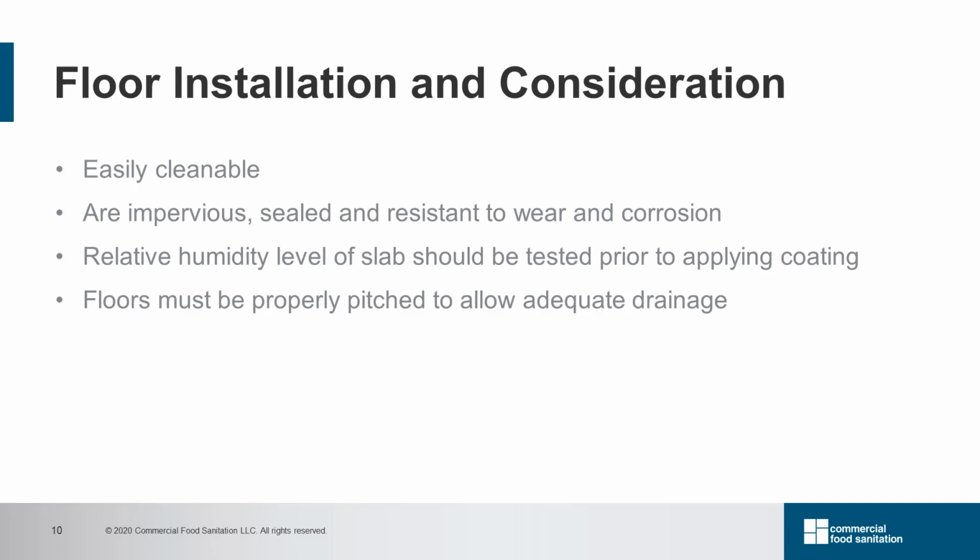In addition, the floor should maintain a certain slope, generally at least 1 degree. That means there is a height difference of 1 centimeter per 1 meter, or 0.4 inches per 3 feet, which is conducive to self-drainage.